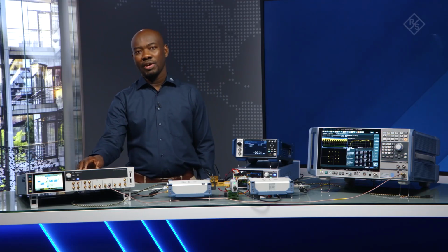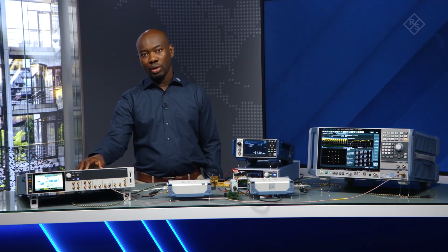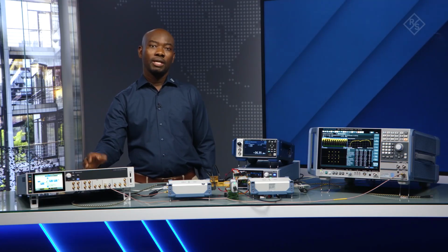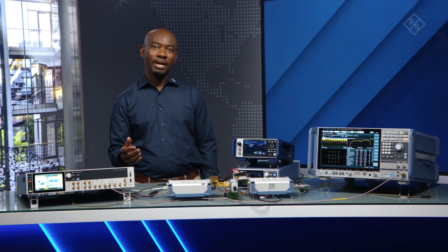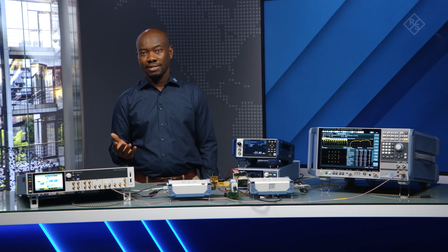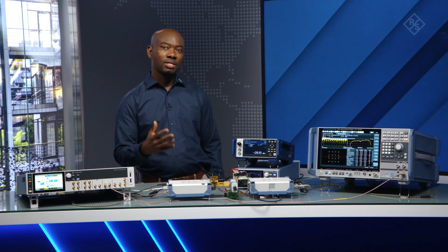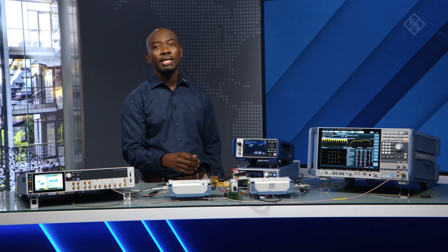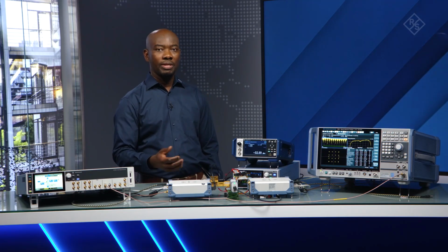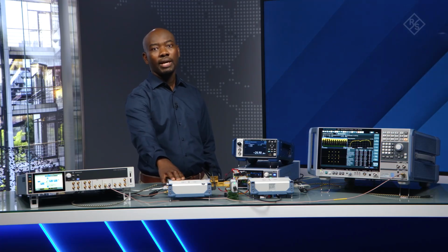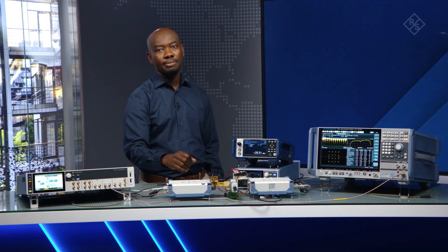The SFI offers very wide RF modulation bandwidth of up to 10 GHz. It covers the frequency range from 11 GHz to 21 GHz for IF tests and from 70 GHz to 175 GHz for tests in the sub-terahertz region in combination with the FE110ST and FE170ST front ends.